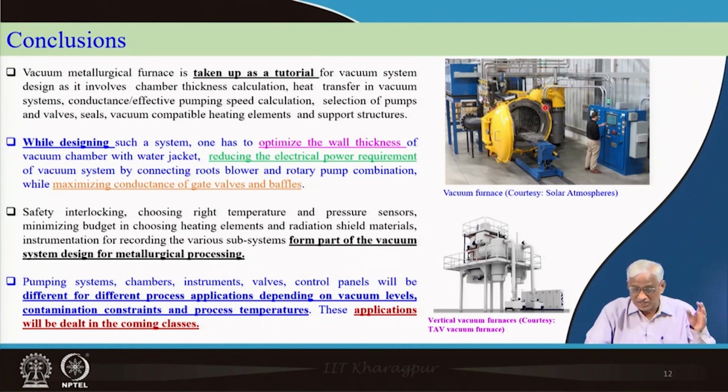Again everything is done, cooling should also be done very carefully. At that time you have to open the door, during that time venting should be done very carefully. If there is little positive pressure, huge amount of force will be there to quickly open and it will hit your face. So, that time use very sensitive delta P indicators, preferably even a water U tube, highly sensitive.